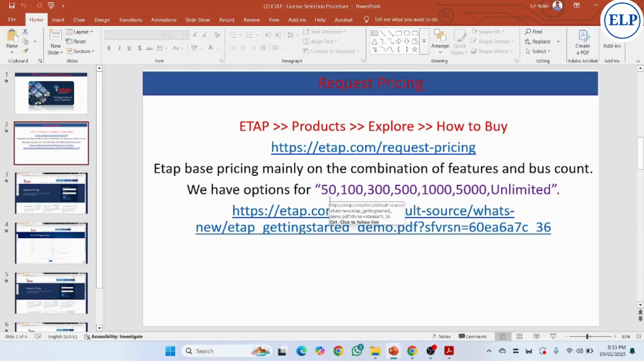In the time of network design, there are no restrictions. The user can model the network with an unlimited quantity of connections. But once you start the process of analysis, we can analyze only based upon the bus quantity. For example, if I design a network with 300 buses, but my capability is only 50 buses, once I start a simulation, ETAP will give you an alert based upon the available quantity in my current license.